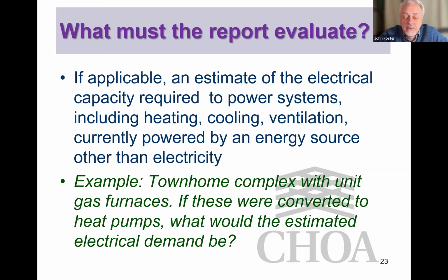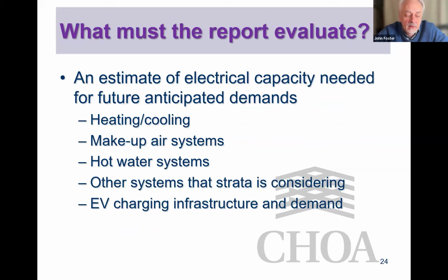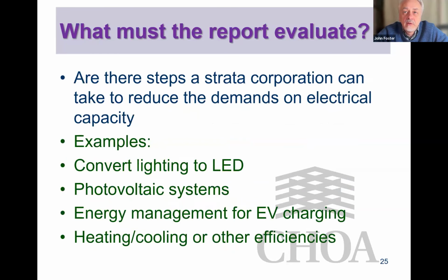You'll get a number of different pad mount transformers on the site, and you'll see that some of them are extremely heavily loaded and others are not. And you also have different demands. Some people are getting electric vehicles over here, others want heat pumps over here. So it is pretty difficult. The gas powered townhomes are the most tricky ones to work on.